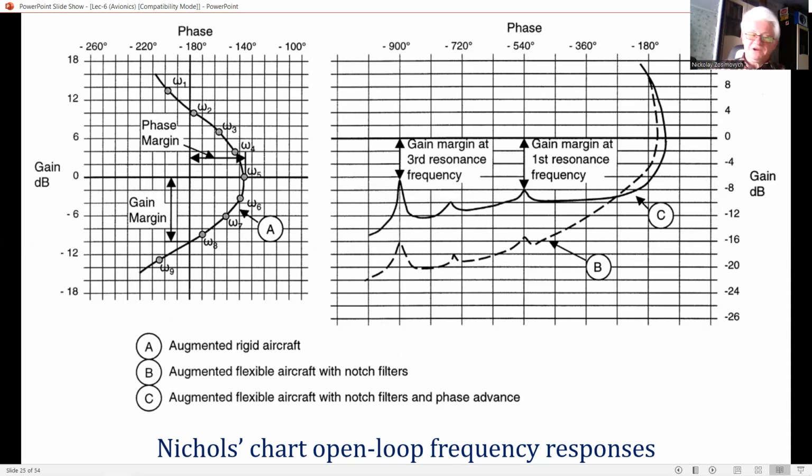Structural resonance frequencies where the open loop phase lag is minus 360 degrees or multiples of minus 360 can exceed 0 decibel gain for this frequency, and the action of the loop is to suppress this frequency.